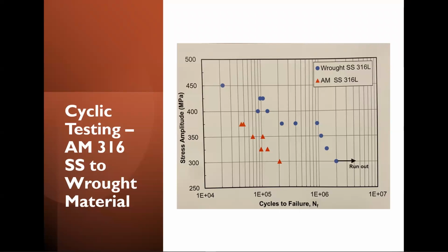So as those are just some considerations, we will have to be doing some data later on, but this is one of the studies that was pulled from Dr. Simsiriwong's lab with fatigue life data generated from additively manufactured 316 stainless steel and the same composition metal as wrought as well. We can see the difference in the two materials and how this kinematic hardening tends to reduce the overall fatigue life in the additively manufactured part.